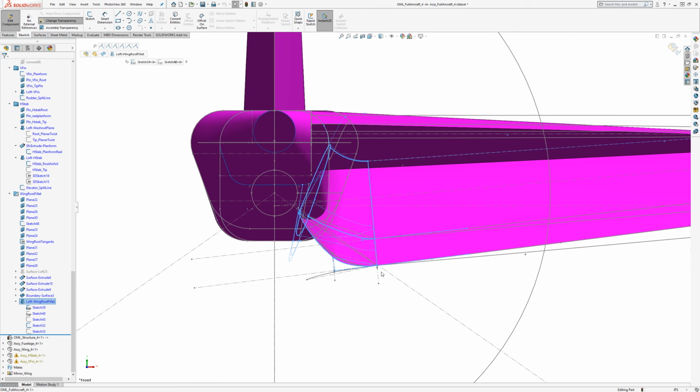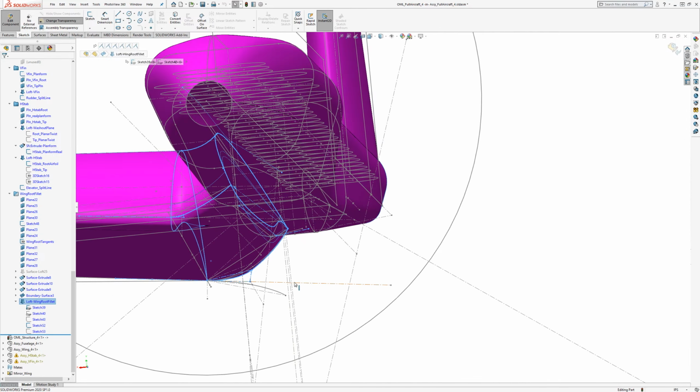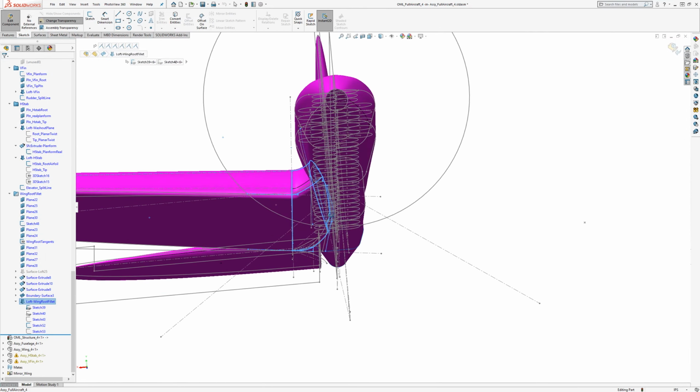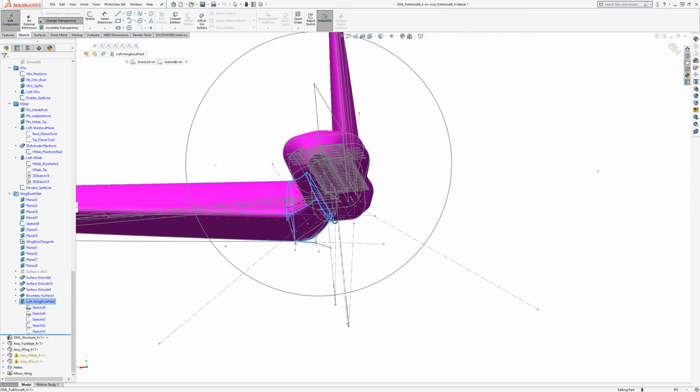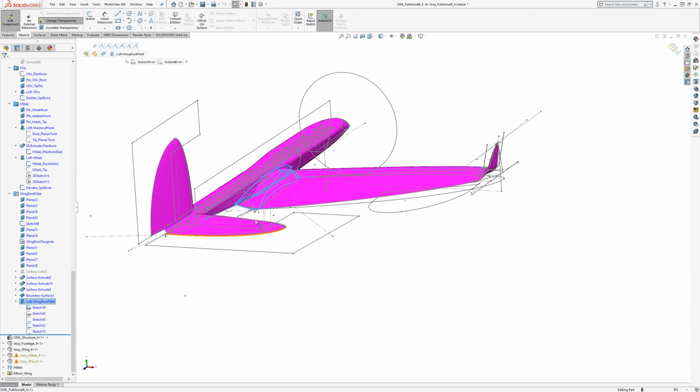Saves a lot of space in the fuselage, but you can see how much of a distance the trailing edge is lower than the fuselage. So what this does is streamlines that airflow in a way that it can go through the fuselage and also over the top of the wing and meet at pretty much the same angle anywhere along this span here.